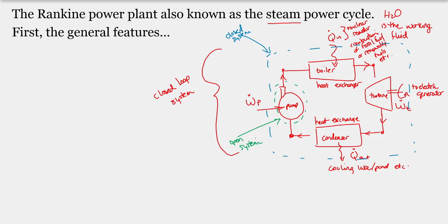Okay, so this is a great example to emphasize that it's important that you define the system well. So if you want to treat the system as a closed system, you need to consider all of the components together. If you want to understand the specific pump work required, for example, you can only identify the pump work if you look at that specific component. If you looked at the entire system, the mass transfer doesn't cross the system boundaries and you wouldn't be able to determine the flow rates for the pump, things like that.